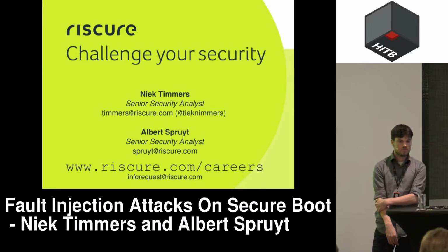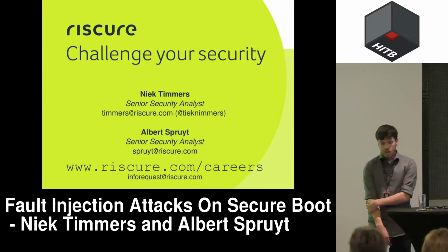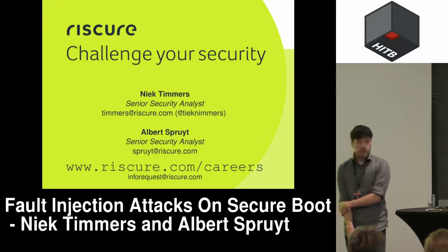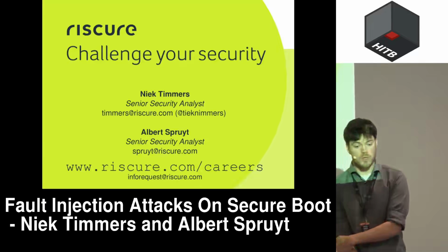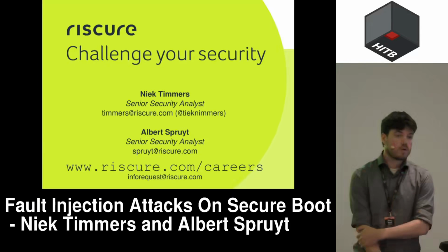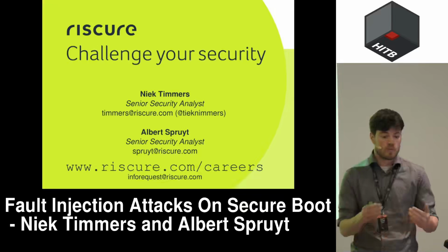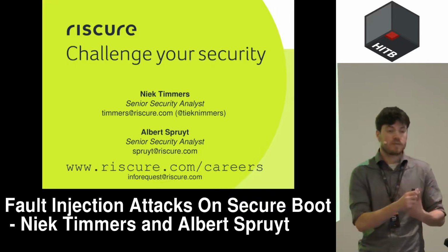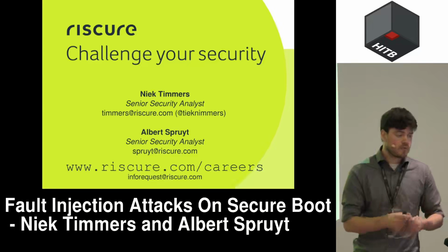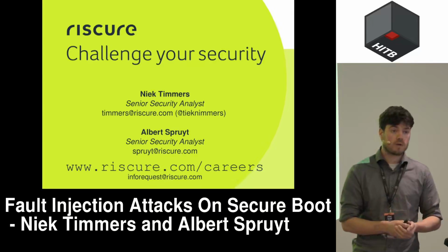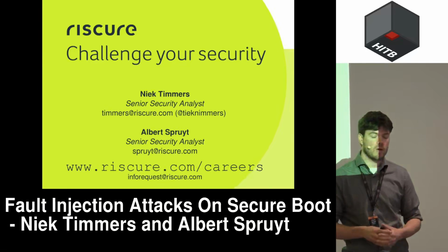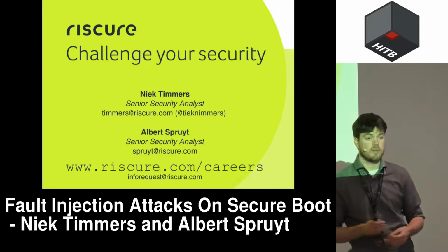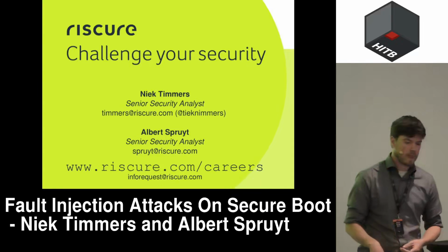For the glitching, is this the Spider enough, or do you need even more things there? I think in the basis it's enough. It depends a bit on your target. I think it also is a question of what the target needs. So you can imagine that if you have a normal embedded system, you might need an FTDI cable. It depends a bit on how much power the target draws, but you might need basically a source that can deliver the amperage needed for that target.